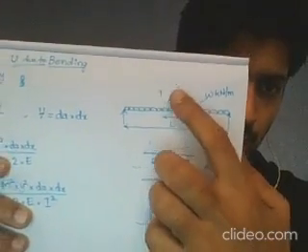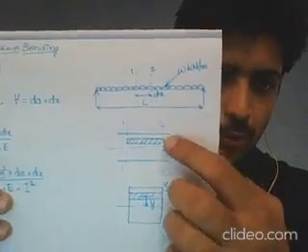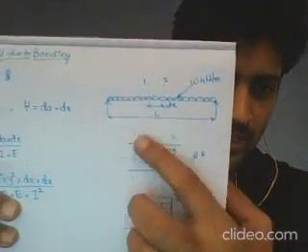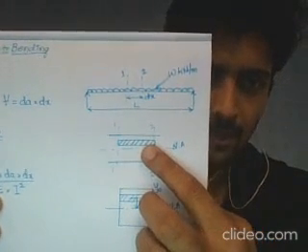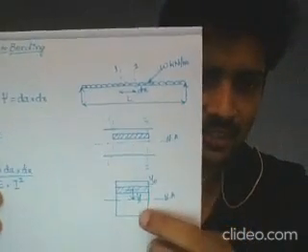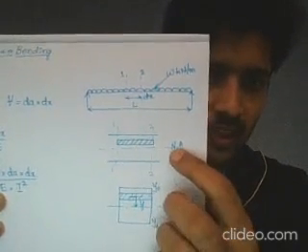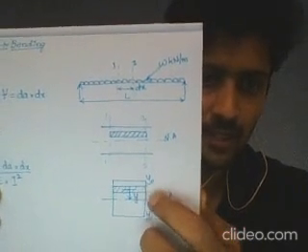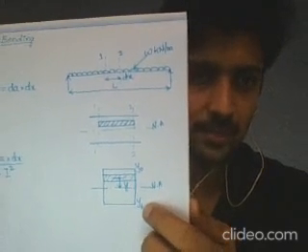If we zoom into this particular area, we can see that there is section 1-1 and section 2-2, which are apart by a distance dx. In that particular section, let us consider one element of cross-section dA and length dx. Let us define the distance of the centroid of that element from the neutral axis as y. The maximum limit will be y subscript O on the upper side, and y subscript T on the lower side.